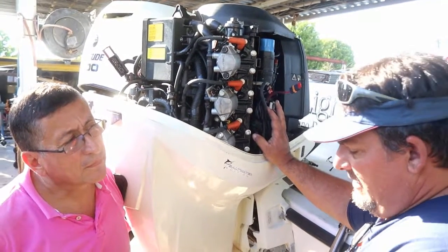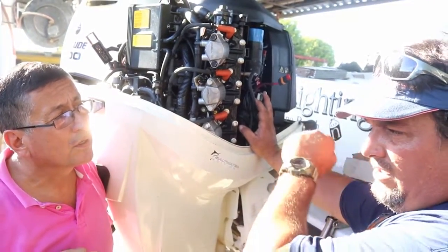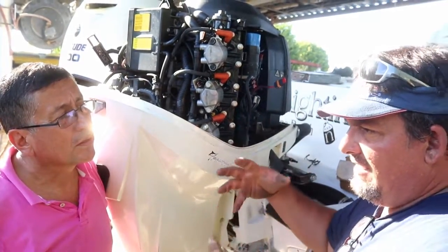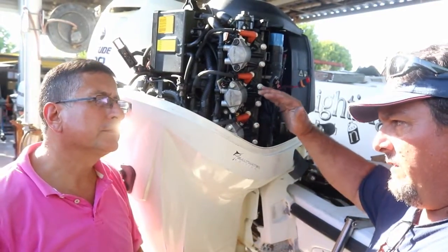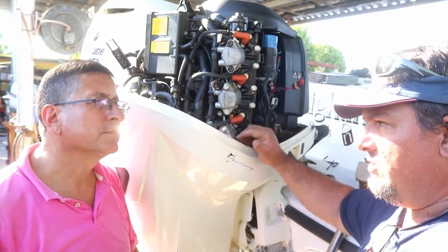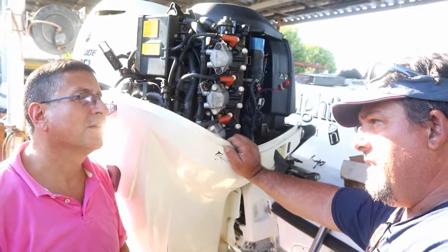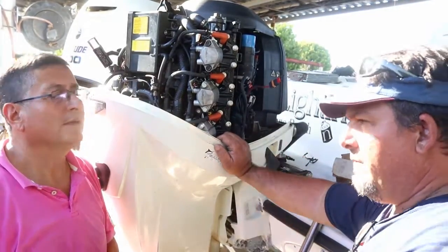And what that does is allow it to engage and disengage. That's the neutral safety switch. Well, no, the neutral safety switch is in the control box. The shift interrupt switch works by killing the engine for a split second to allow the gears to engage and disengage. Correct. And if that's holding too long, it'll affect your ignition. It'll knock out one bank of the engine. That's why it's important you do a spark check. If you only have spark on one side, more than likely you have a problem with the shifting.